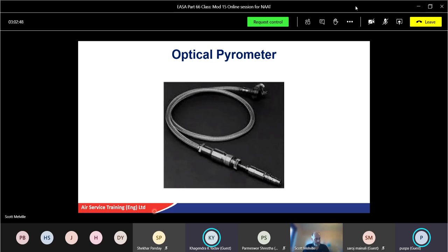It controls the amplifiers. What does a trim resistor account for? Now, every trim resistor on each engine will be slightly different. Same as the ballast resistors, they'll be calibrated for that specific engine to do the same job. But the ballast resistor did the balancing for indication. The trim resistor compensates for a small variation in the system resistance.